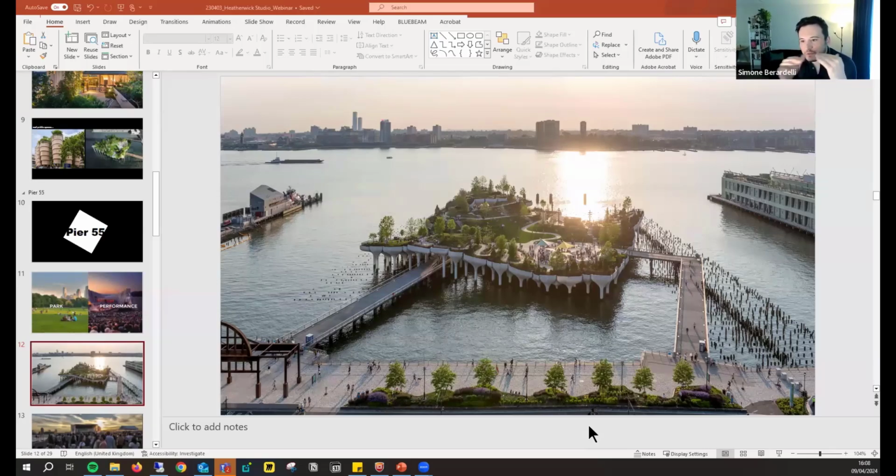But when I'm referencing that into Rhino Inside, it will create a toposolid which is essentially a mesh. It will triangulate the matrix of points that I reference from Rhino to then create a mesh that is like the reference for Revit. So the answer is a bit of a mix. It's referencing a NURB, but in the end for Revit it is a mesh.